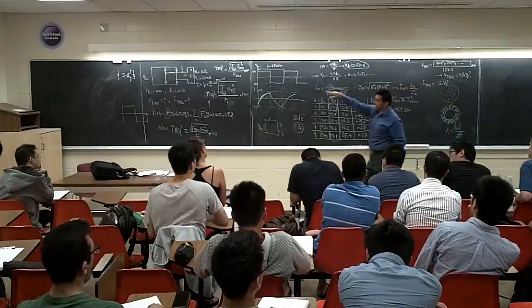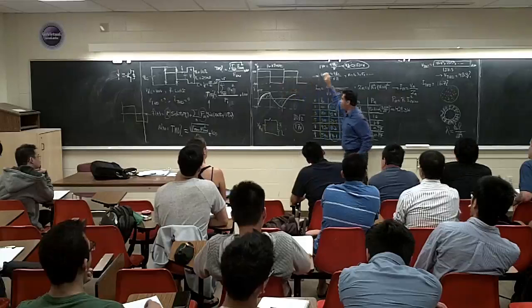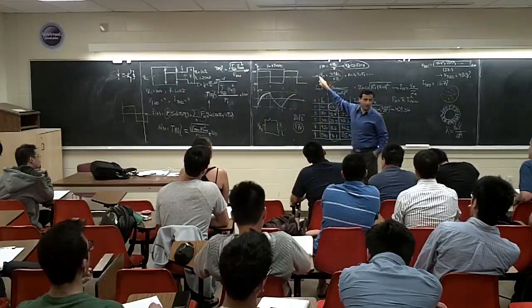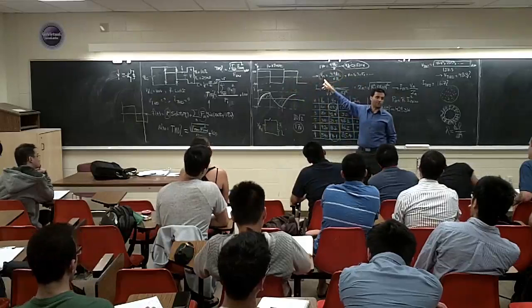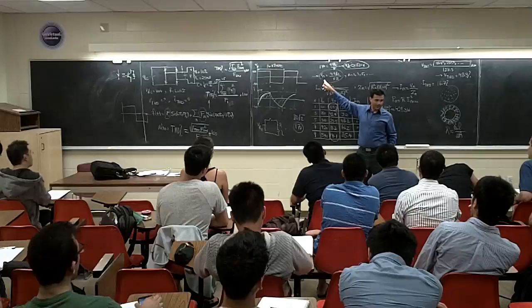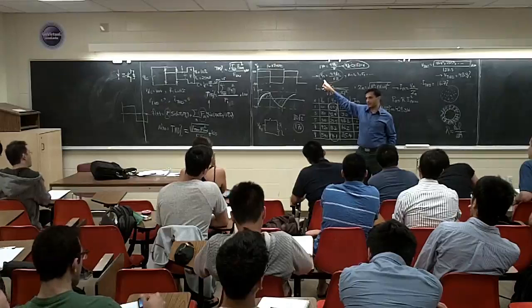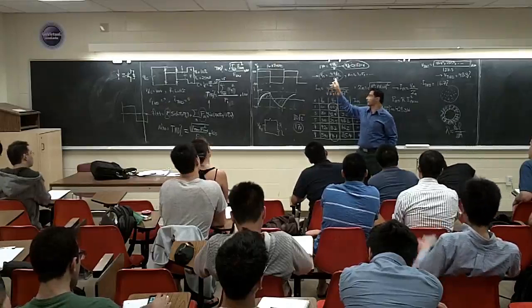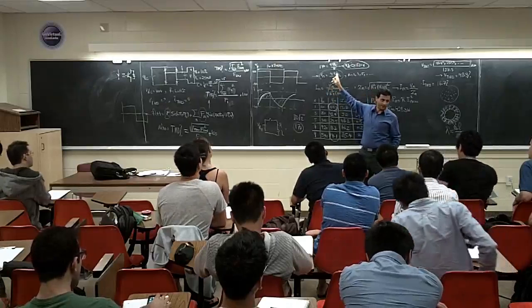You say, okay, if I'm going to use this 50%, so at least from this equation, the V1 I know how much I want for my V1. How much do I want for my V1 at home? 110 volt, right? Everything at home is 110 volt. I want 110 volt, so with 110 volt I can calculate how much battery I need.